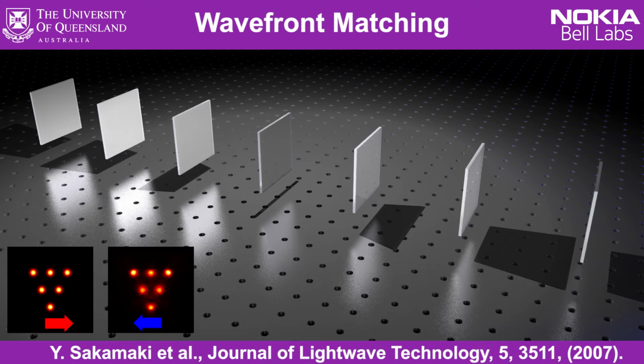In practice, the fewer phase mask planes you can get away with using, the better, for several reasons. First, because it makes it smaller, cheaper, and easier to actually make the thing. And second, because these MPLC devices are theoretically lossless, but in practice, the loss is going to scale with the number of optical surfaces that the light has to travel through.